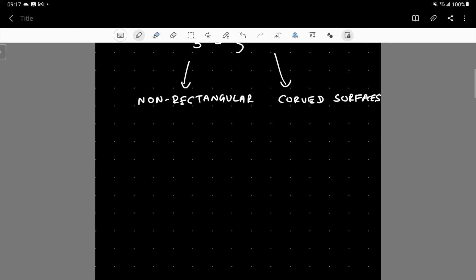So when you're using higher order elements, the set of equations behind the finite element formulation, especially when you're using a global coordinate system to express this, becomes complex. That is why we use isoparametric formulation, to make our life easier. And also most of the commercially available finite element based simulation programs have incorporated this isoparametric formulation of finite element based problems into the commercial packages.